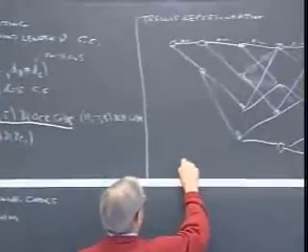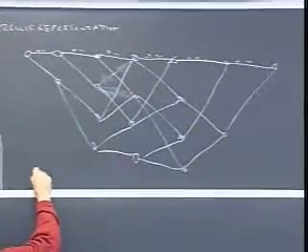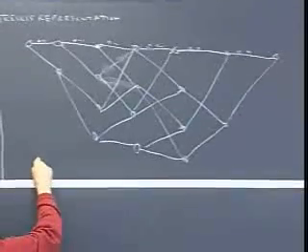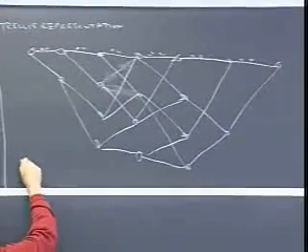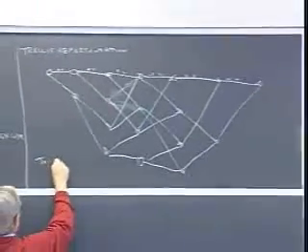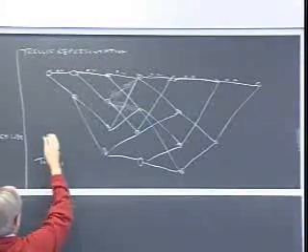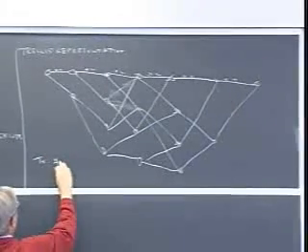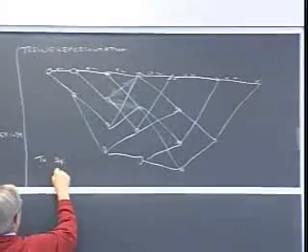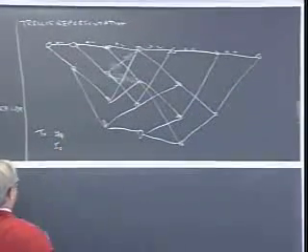We're going to assume that each time here we get to see two things, corresponding to the 2 bits we transmit. So we transmit yk according to which trellis branch we're on, or y0 at this point, and we receive a two-tuple r0.